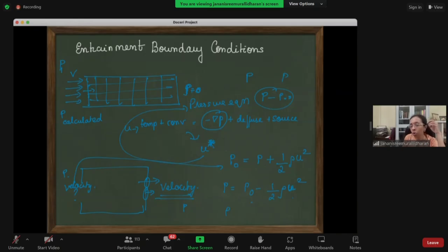So with the stagnation pressure, I am giving a little bit of room for flexibility of iterative solving. Rather than fixing a static pressure, you get that pressure to be calculated by a guessed U. So there is a little bit more flexibility.